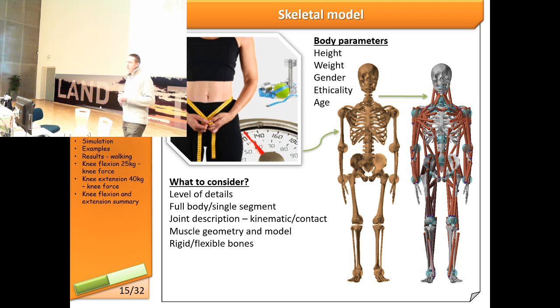And then you have to decide also which bodies you model as flexible and which should be rigid. Flexible muscles or body parts will give you information about internal stresses, which is quite useful, but where you don't need it, you should use just rigid bones to support the body, because of the computational expense, and of course the preparation time for building the model, which is elastic. That might be an issue.